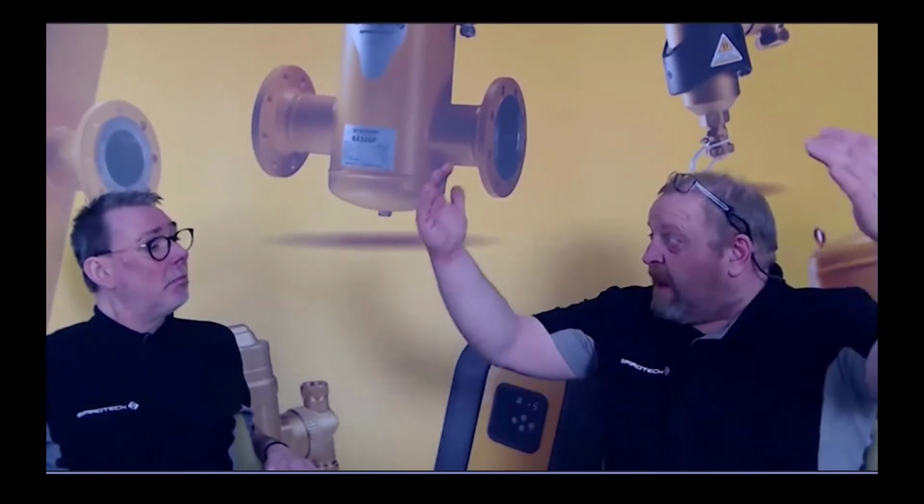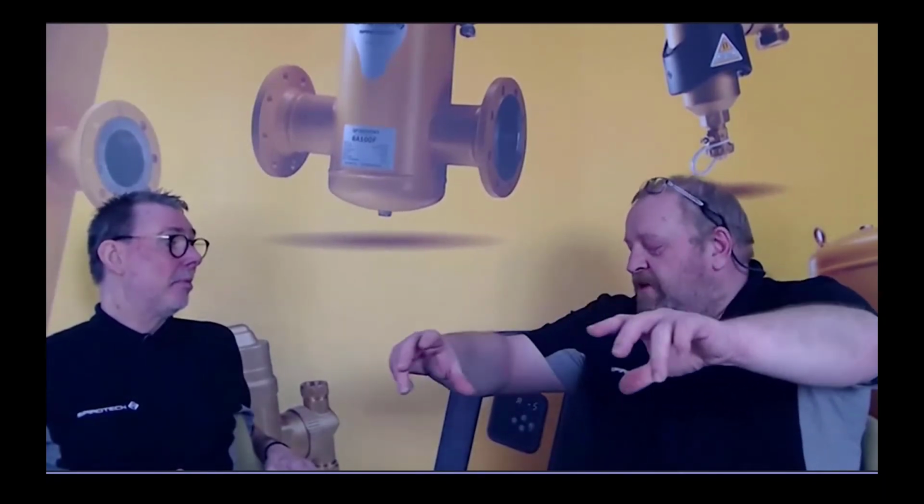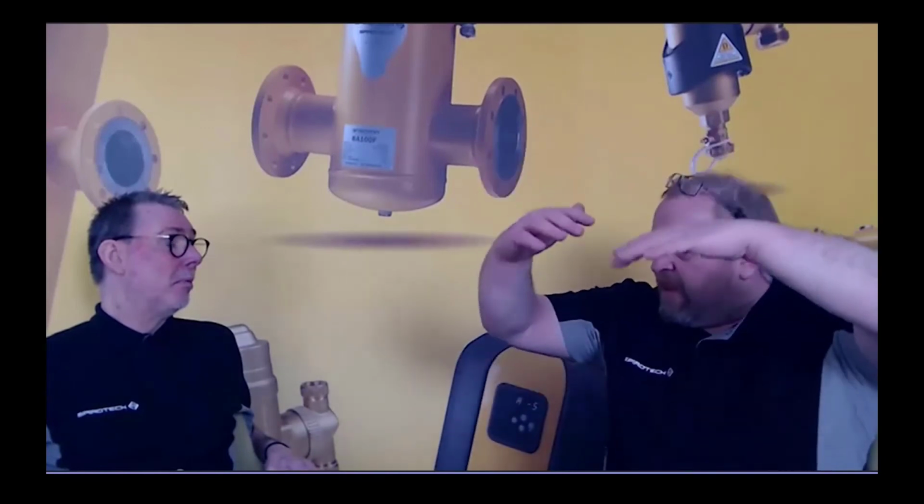Once you've got that water in the system, next level up, you've got to get everything in the correct pressure position to prevent air coming back into the system. Obviously, you've got to have a system that doesn't leak, so that you're not continually adding fresh water to it. So you put it all in, then you get the pressure right. Because you've got the pressure right, you haven't got the air coming in. You therefore get rid of whatever gases you've got left, and the whole system runs more efficiently because you've got the water right, because you've got the pressure right, because you've got the aeration right. The corrosion is going to be severely limited.